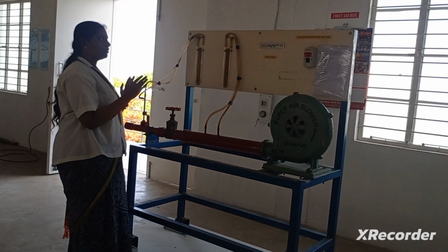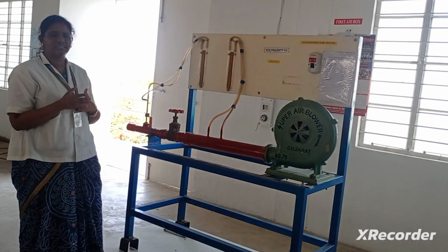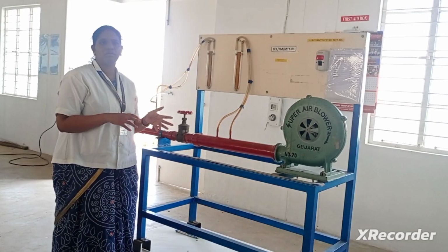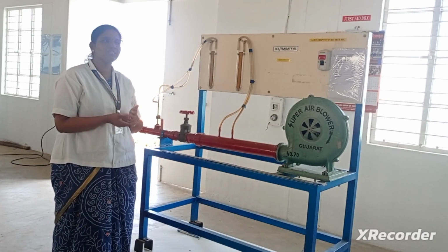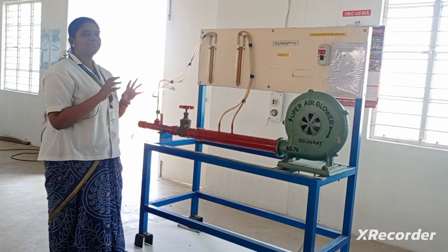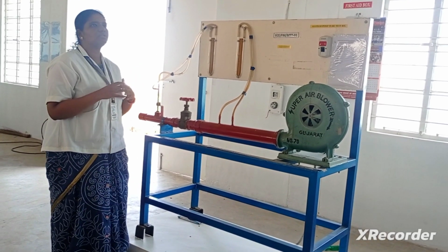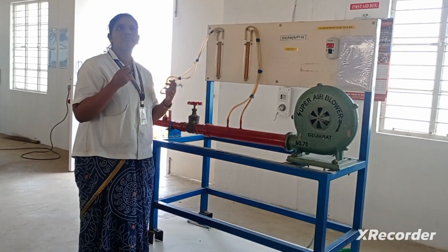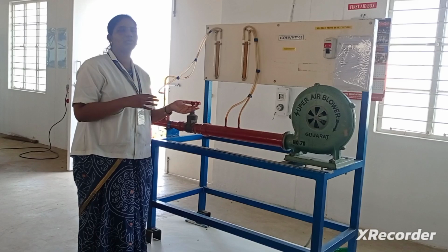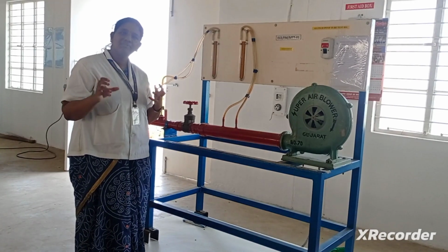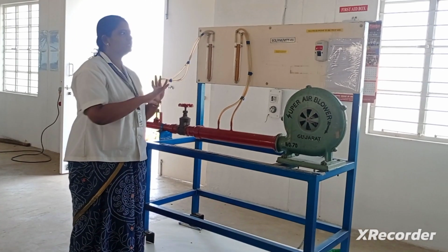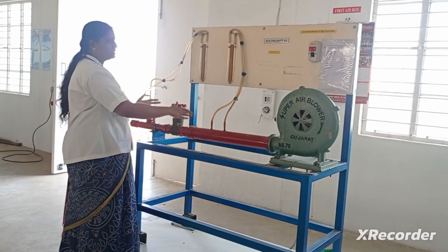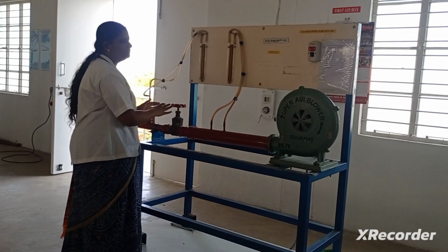Then, to identify the different velocities, we are going to use Bernoulli's equation, which we already studied in your hydraulic subject. With Bernoulli's equation, we have to get two different pressure values, which are considered as P1 and P2. From these two pressure values, we are going to calculate the velocity. From the velocity, we are going to calculate the mean velocity of the whole setup. For that, we are dividing this into two sections: without resistance and with resistance.